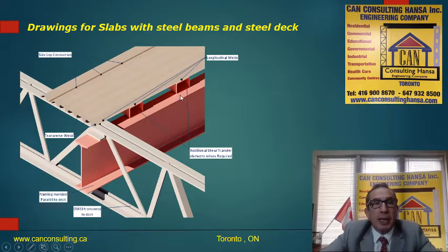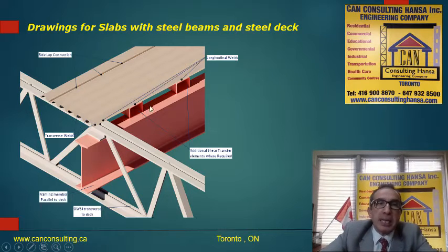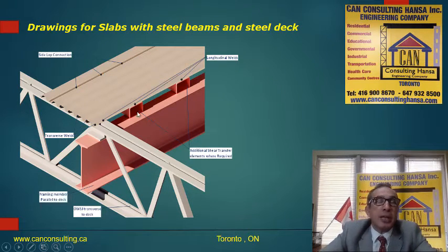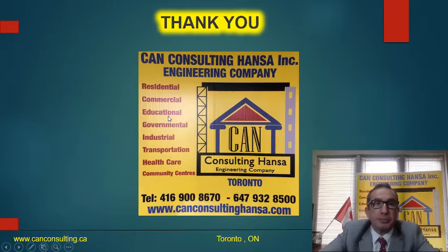Now, if you have another framing system, which will be steel beams or girders, and then you have a steel joist at the edges here, you can see the difference between the top levels. In this case you have to provide additional shear transfer at specific intervals, and then you can connect your steel deck to the shear transfer, and also you can weld your steel deck to the joist.